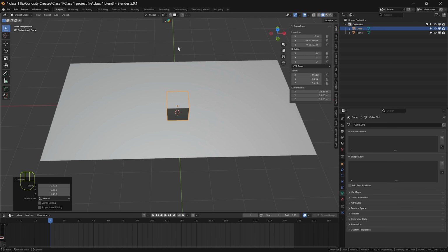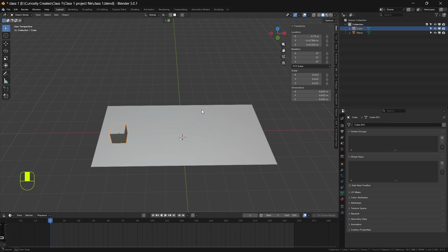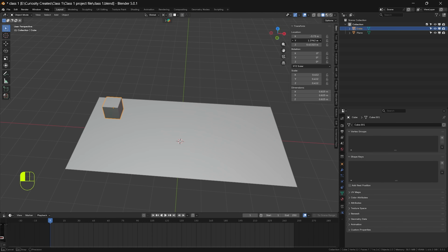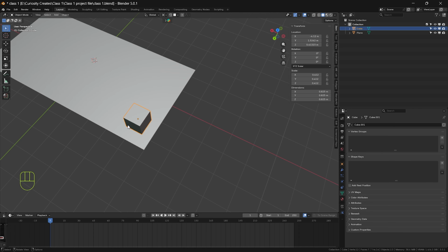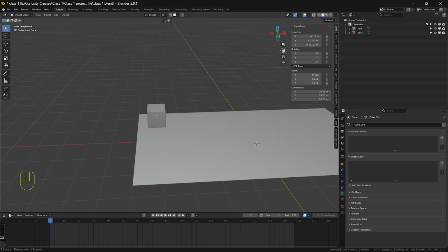Finally, let's park this cube in the corner. I've taught you the G shortcut, but sometimes the menu is just easier for precise parking. Go to the Transform menu, left-click on the X value and slide it to move the cube sideways. Then left-click on the Y value and slide it back. Let's tweak the X position just a tiny bit more. Rotate your camera around to inspect your work. And I think that looks solid.